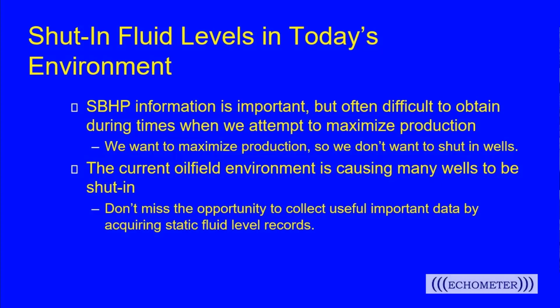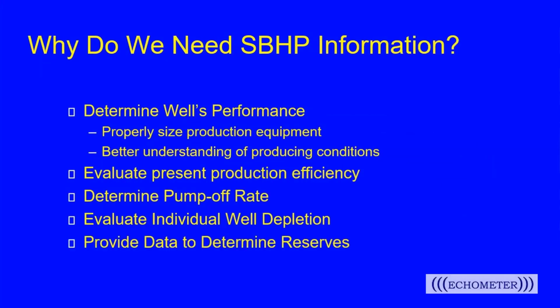But these days we're shutting in wells anyway because of the current environment, and we may have a better opportunity to get the static bottom hole pressures or shoot fluid levels on shut-in wells. So that's an opportunity that we just don't want to miss. We'd like to take advantage of that opportunity.